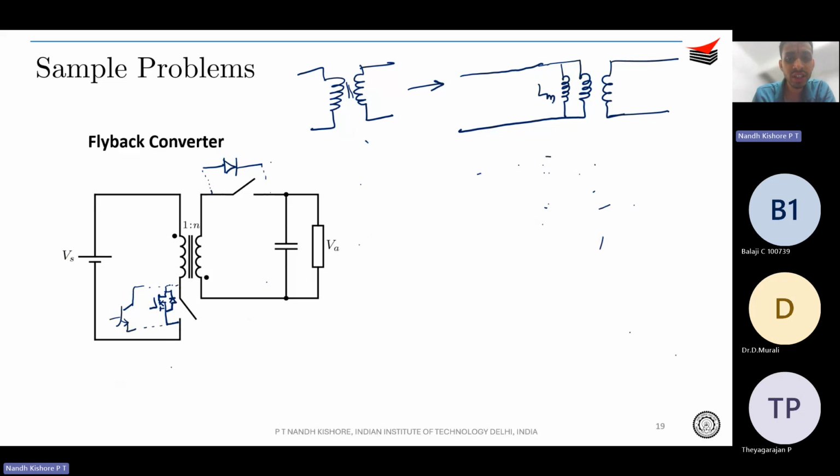For instance, in the BH curve, while you expect to operate in this kind of a fashion, initially you need to magnetize it, and then you see that there is this residual magnetism. So this residual component, or whatever is the flux required to achieve this residual component, we represent it in terms of the magnetizing inductance.